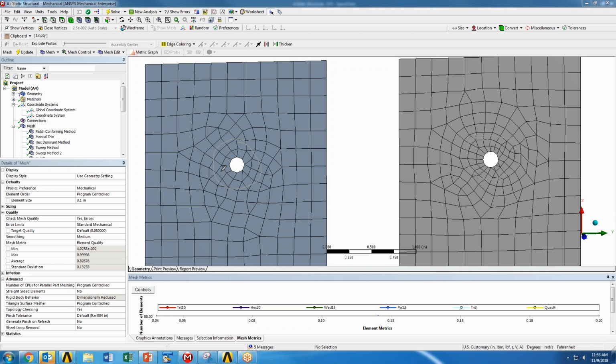And oftentimes, if I'm running a job with a lot of holes, usually I'm okay with six elements around a hole. And if I'm truly interested in it, I can just go to that specific hole and add more elements, right? Because you'd be surprised, it doesn't look like much between these two plates, but if you have many of these holes, you'd be surprised how quickly the difference of the element numbers between them adds up. All right, so this job on the left, let's say it's going to total 200,000. Job on the left could be 350,000 elements, right, which has a dramatic impact to runtime.